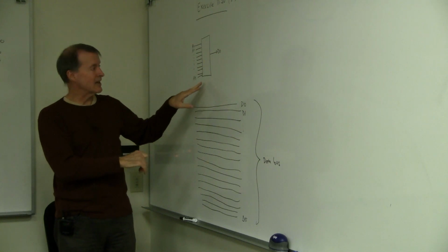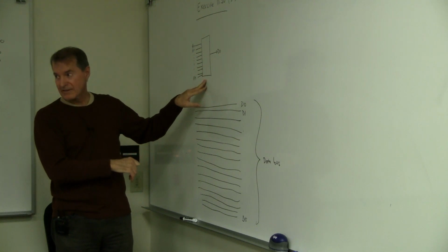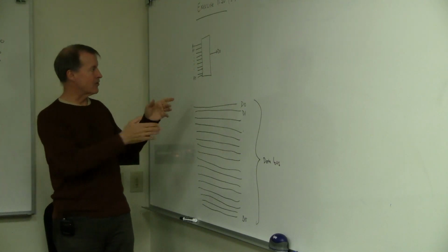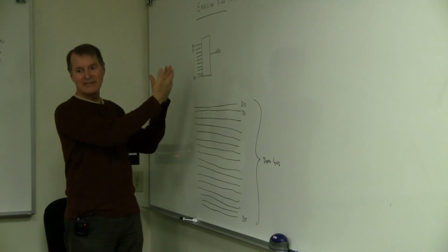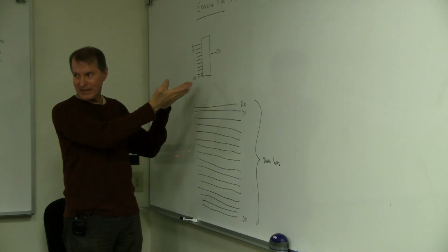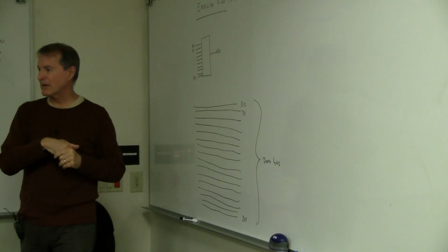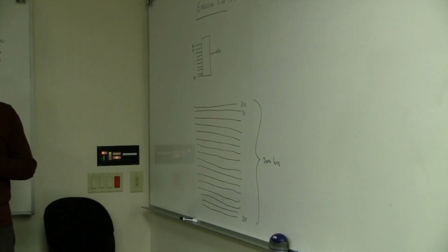And so therefore you're going to need how many chips? 16. So you keep that number. Now you've got 16 chips. You know how many bits are in each one, so you know how many bits total are in your memory, and then divide by 8, that is, divide by 2 to the third. If you do 1K by 16, divide by 8, because that's how many bits are in a byte. So you divide by 8 to get how many bytes.